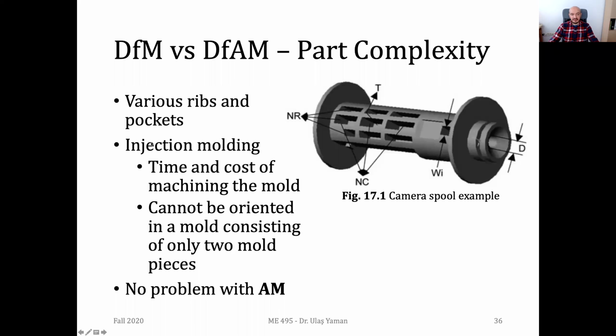But if you want to do it with injection molding, then you may need at least 3 manufacturing sequences, since in a single mold, I think at maximum you can have 4 products. But with additive manufacturing, you can have more than, let's say, 10, maybe even 50 products produced in a single batch, depending obviously on the size of your spool.